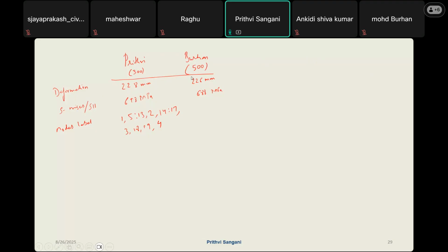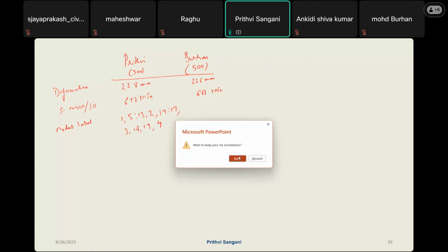That's again, we'll discuss when you all have this software installed. Maybe in our next class we'll discuss this mesh convergence. So for now, just keep this in your mind: your results are very mesh sensitive. It is sensitive towards your mesh size.